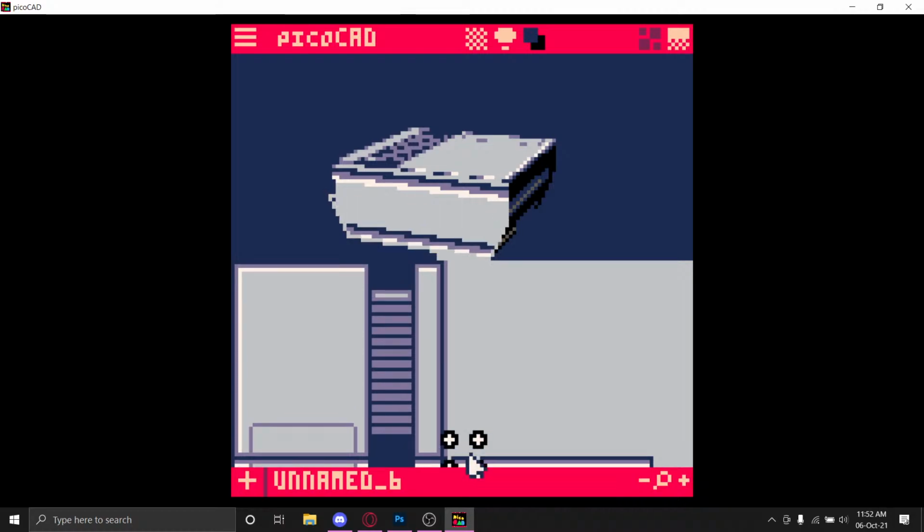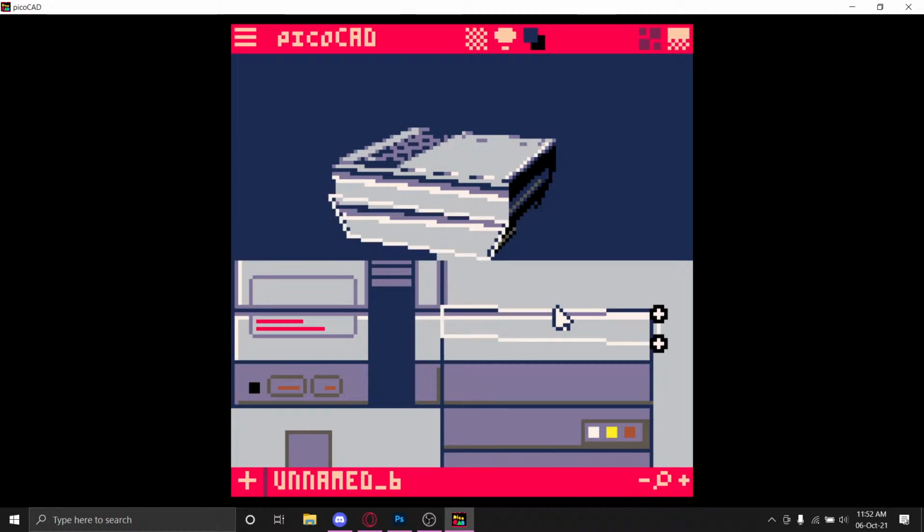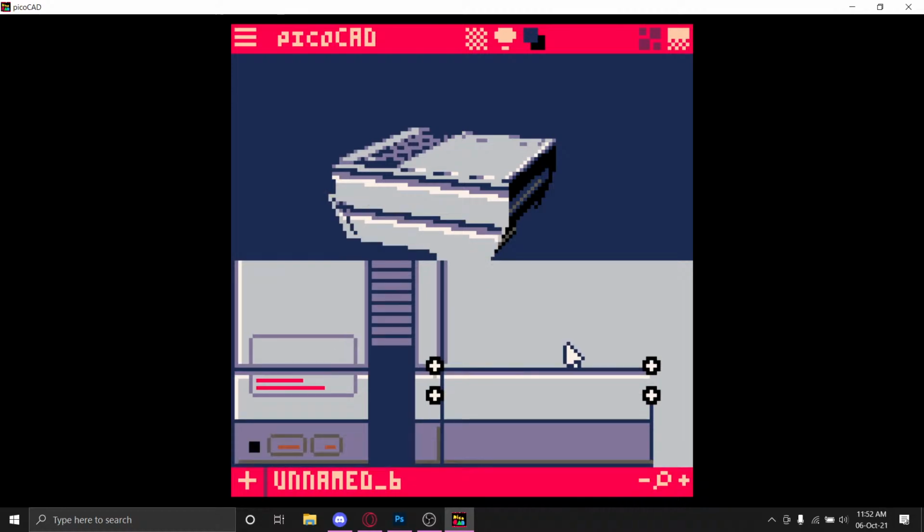No, just move back up. Hold X, select these 2 points. Use the arrow keys to move them. Right. And again, if I move them, since we want the border, we can move this by 1 and move the entire thing, hold X, and move the entire thing by 1 in that direction as well.